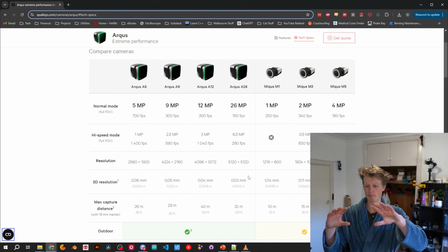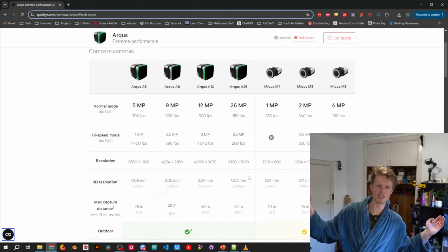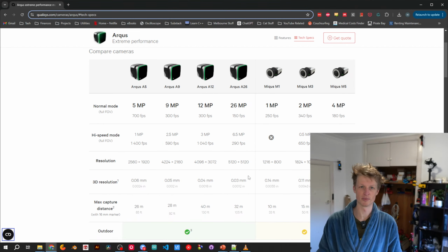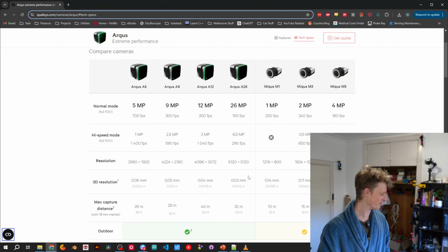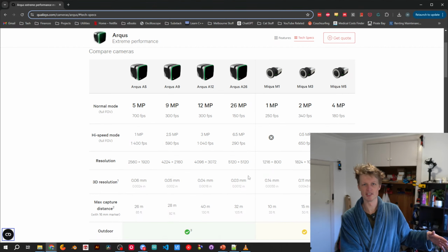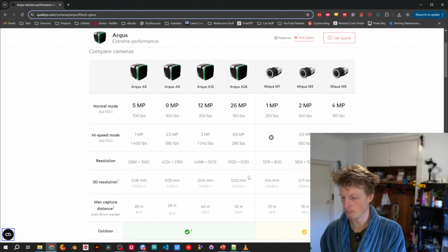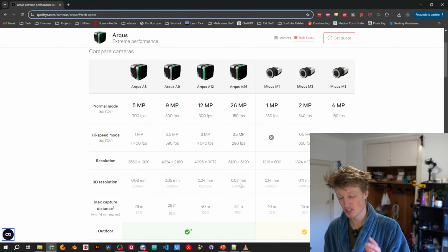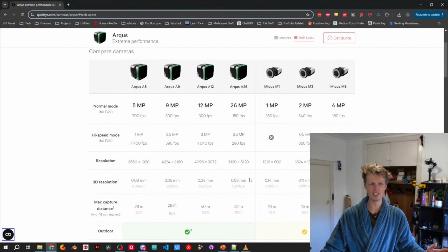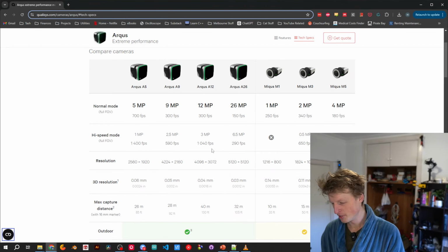and then basically do the simulating errors approach. So we simulate a bunch of different geometries of the platform, maybe using this hybrid genetic algorithm if I can figure out how they've actually done that and what that actually means. But in some way, just try a bunch of geometries of the robot and see how accurately they can match the observed positions, which should be extremely precise, like 0.03 millimeters. While it's not the 0.001 millimeters that the paper used, still pretty damn good.